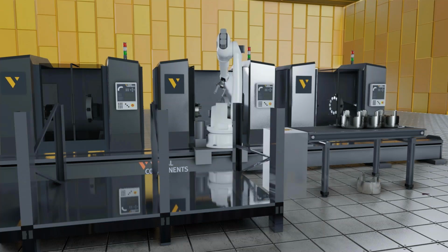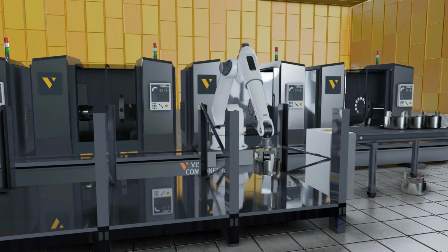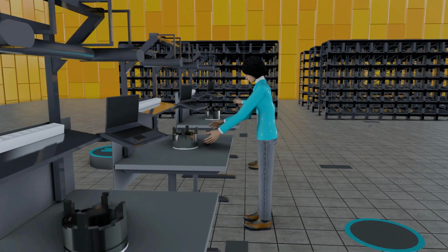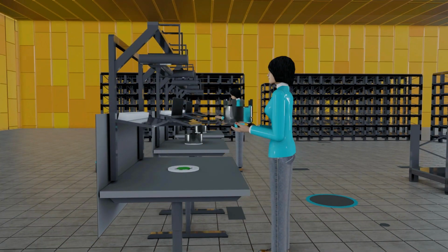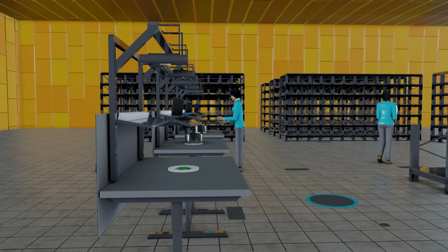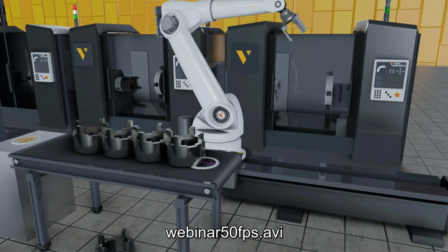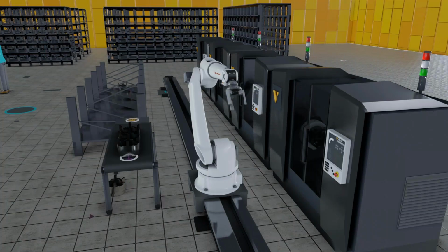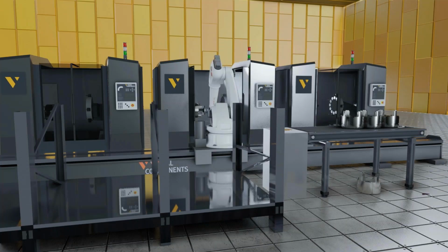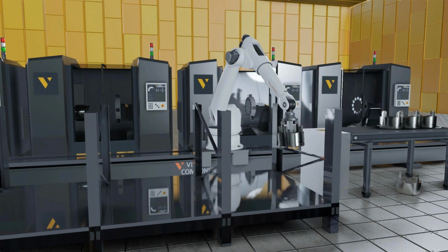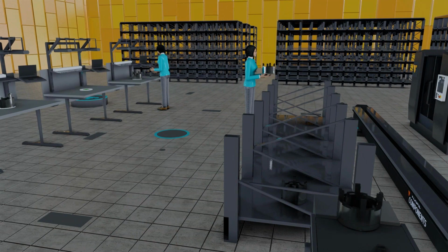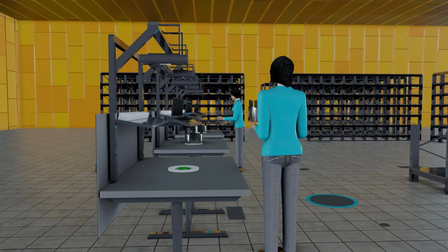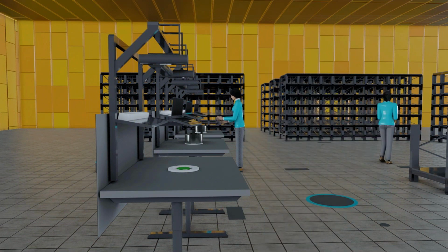There is, for example, a question about the possibility to simulate flexible product flows on conveyors, meaning plastic bottles for soaps or something like this that would accumulate. If you accumulate them for too long a distance or time, you could create too much back pressure and damage the products. So we're not doing this kind of simulation. We can do physics-based simulation, but only with rigid bodies. You could, of course, create some sort of formula in Python with component modeling, if you know from practice how much queue pressure you can have without damaging the products, and then you could have a warning if the queue is too long.